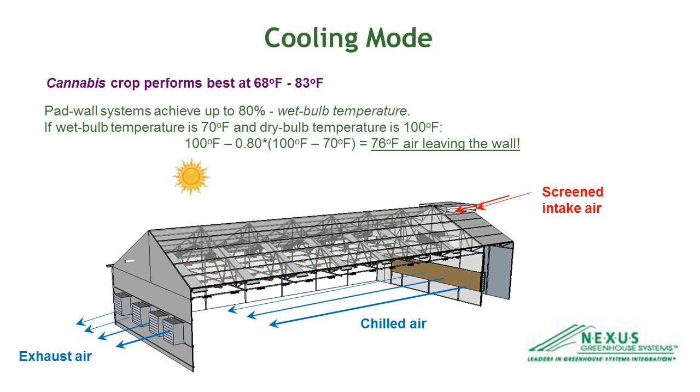So I would just like to explain a little bit, maybe cover wet bulb and dry bulb and what that really means, just so people make sure they understand it. Dry bulb temperature is just an ordinary thermometer. Wet bulb temperature is actually a thermometer wrapped in wet gauze. And the difference between the two will tell you how easily water will evaporate into the air. That's correct. It's an indicator of the amount of humidity that's in the air.